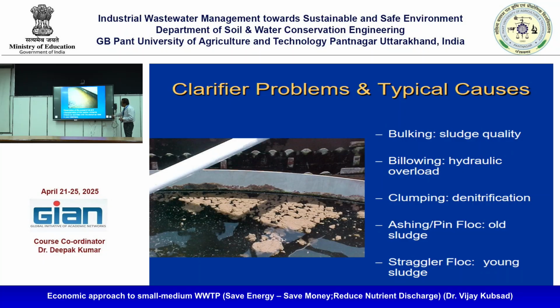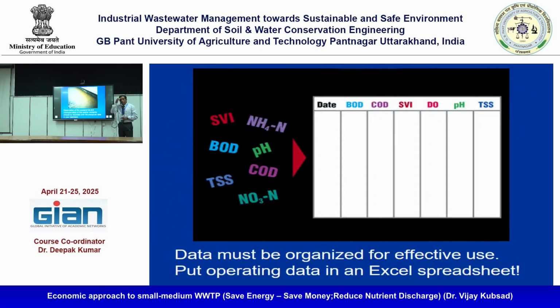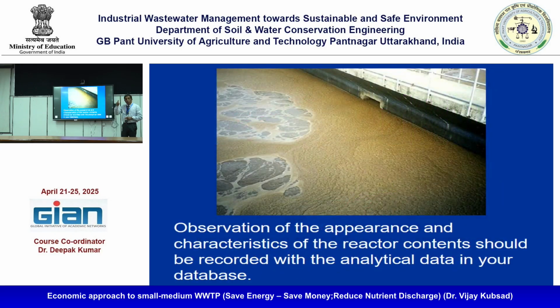You will have to observe the biomass health all the time. Before the complete damage occurs, you should be able to do something to fix it at the initial stage. Otherwise, if the treatment plant is not working, what happens? You will have to do a bypass. You can't even do a recycle, because the plant is not working, and until there is a recuperation, you have to bypass and leave it somewhere.